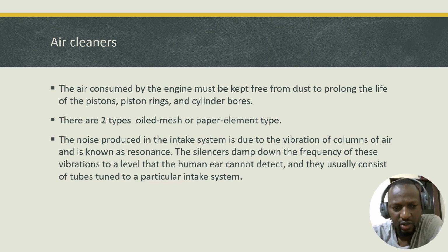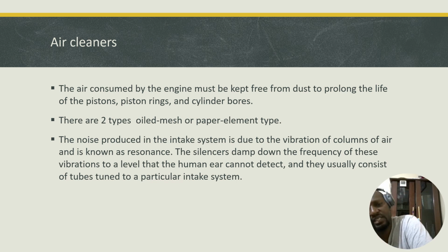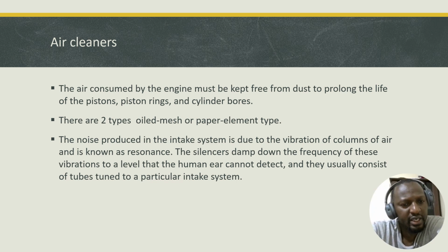Now next I want us to talk about air cleaners. Why do we need to clean the air that comes into the engine? Now the air consumed by the engine must be kept free from dust to prolong the life of the pistons, piston rings and cylinder bores. So you'll agree with me when you say that the air that surrounds us is full of dust. When you try to clean your nose in a handkerchief in the evening, you always find evidence of dust in your nose. Where does this dust come from? These are dust particles that flow in the air.